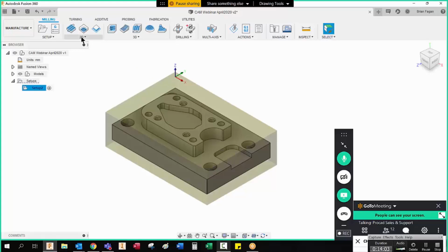And to just show you how easy it is to do toolpaths, what I always do is select a toolpath, select a tool, pick a geometry and press OK. See what the tool does, and then I work backwards. If I wanted to speed up the machining time, or cut in different directions, I'd go back in and manipulate it, and I'll show you how to do that.